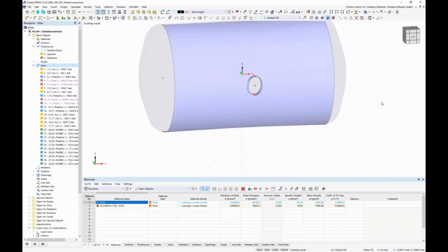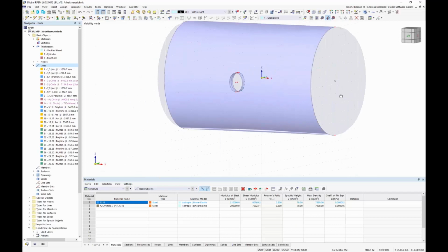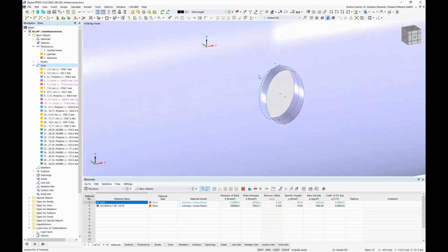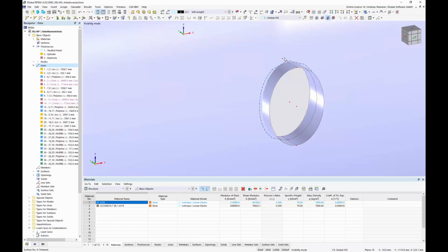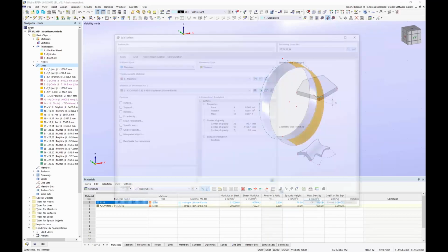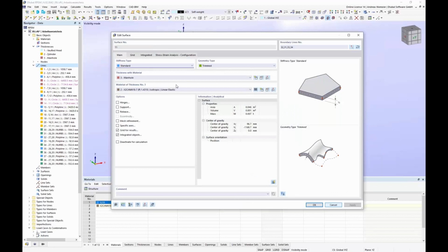With using this command, you see now we can look through, and the program created a three-dimensional opening on the hull of the cylinder and cut this elliptical shape into several parts, which I can open and assign new properties, thickness, mesh refinement, whatever. It got a new type, trimmed. So it's a new surface which you can use for all other things. You can copy, drag, whatever, but it holds the shape from the intersection. This is a really powerful tool, I would say.